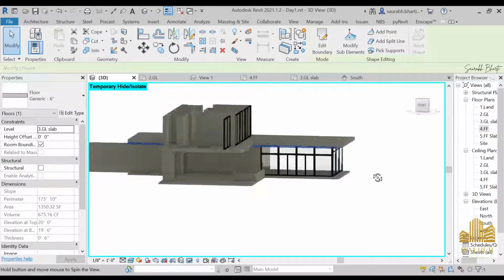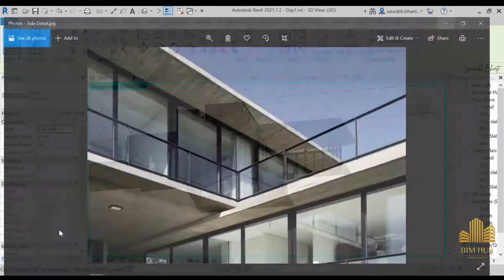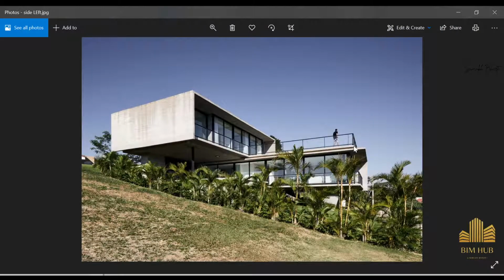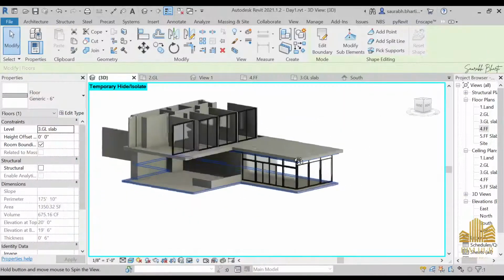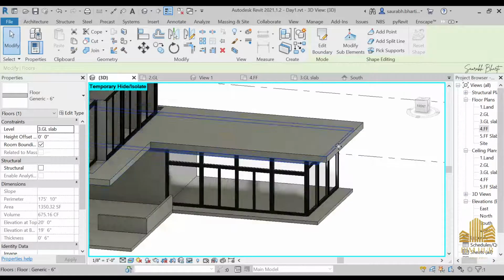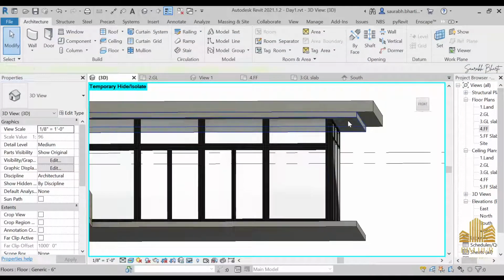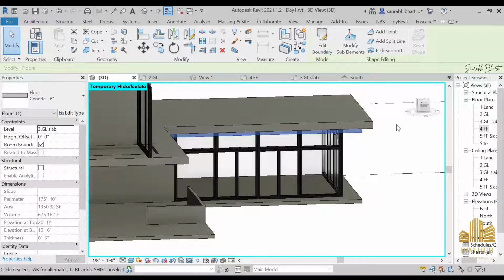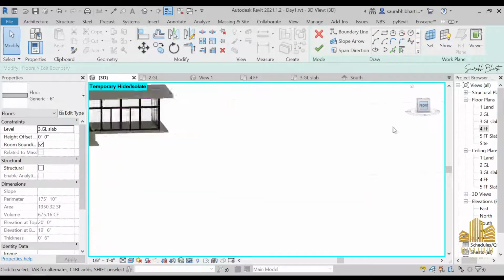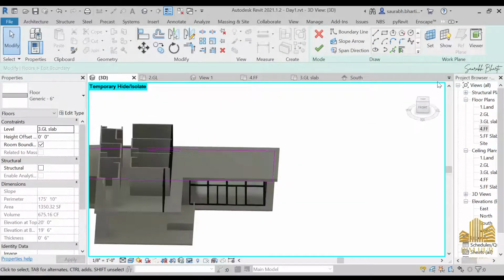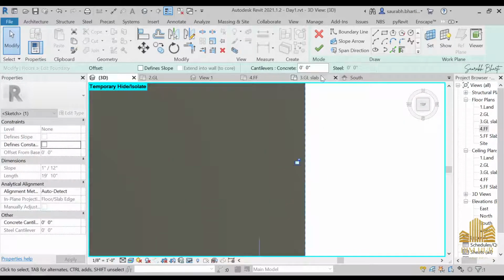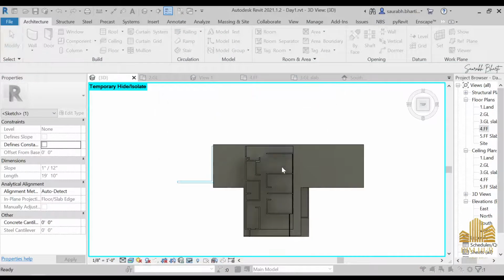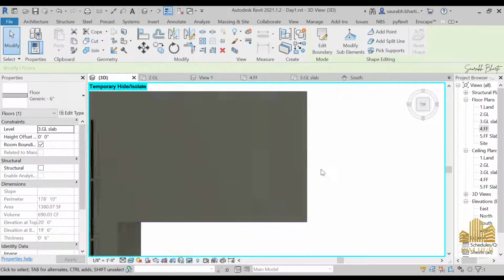And there's one more thing, if you can see it from here, that this floor is still only till this place, and this floor is coming till outside, till here. Okay, so let's just do that one first. So the lower floor, let's just increase the size of that floor. Go to edit type, go to the top view, and increase the size of it till here. Finish it, attach, finish, delete elements, done.